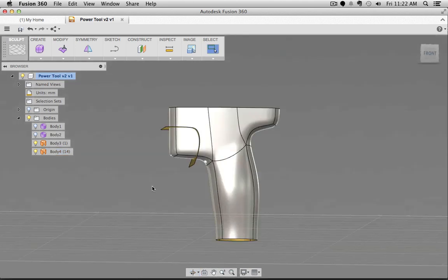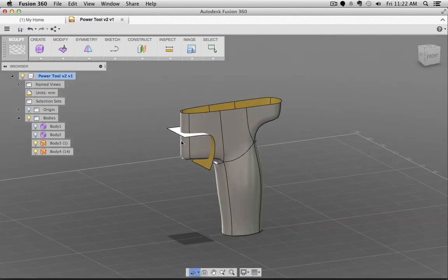And with polygonal modeling, I can easily select a face and extrude something out. And that is something I cannot do with NURB surfaces. But what I can do with NURB surfaces is I can, for example, like here, intersect two surfaces and then let the math code calculate how, for example, this surface intersects with other surfaces and where it intersects, think about like a scissor, we just cut everything off.